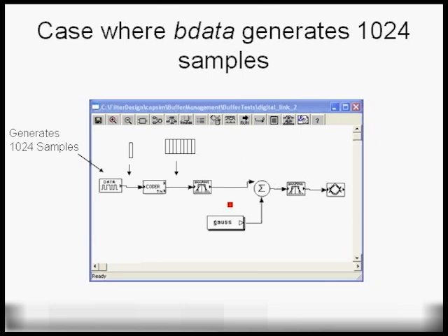But in this case, because of multi-rate signal processing, we'll have a buffer overflow on the output of the square root Nyquist filter here, because the add block doesn't consume all its samples. It only consumes the minimum available number of samples between the buffers, which is limited by the Gauss block, which only generates 128 samples. So in the next section, we'll get into a nice, straightforward solution to this problem.